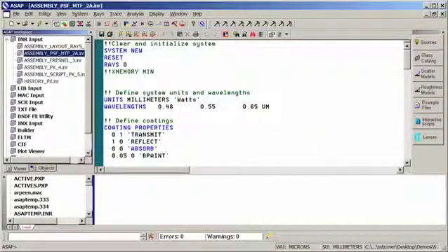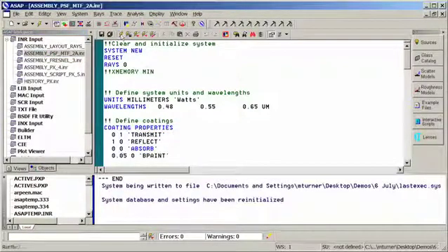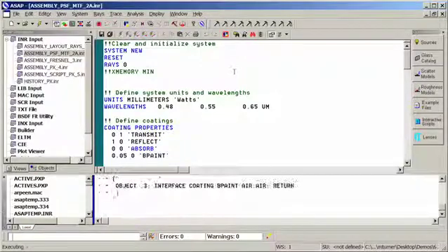Next thing we're going to perform is to look at a point spread function and an MTF calculation performed within ASAP. We can then take this information and compare it to the data from the original optical design program to make sure that indeed the translation was proper, the mechanical structures aren't significantly impeding the performance, that the optical materials are properly defined, as well as the optical components. I'm going to run this file and we'll take a look at the output.